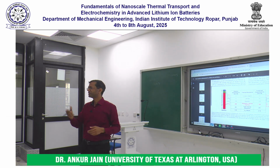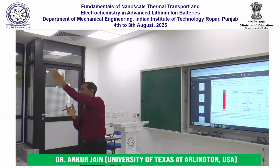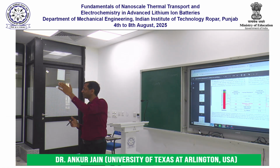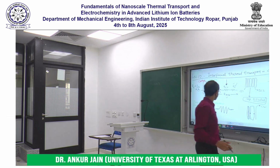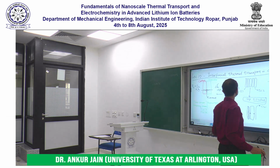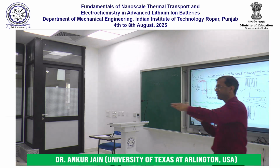Somebody asked me yesterday or the day before, how is the separator and the cathode put together? Is there some glue between them? Do we put some kind of epoxy between them? No, the answer is no. They are simply stuck together at high pressure. So those four or five sheets that make up the cell, we bring those sheets together.